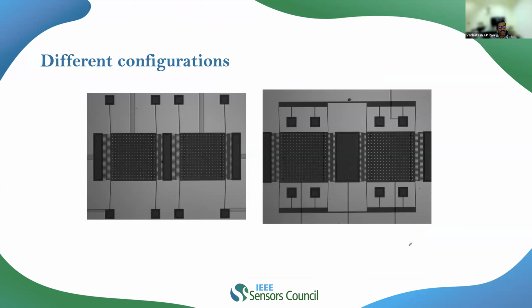So these are some of the fabricated devices. This is a gyroscope with a hammock suspension, wherein I have these drive resonators for the driving, and for sensing, I have the bottom electrode. Can you see this electrode line over here? These are the bottom electrode lines, which are just below this, right?